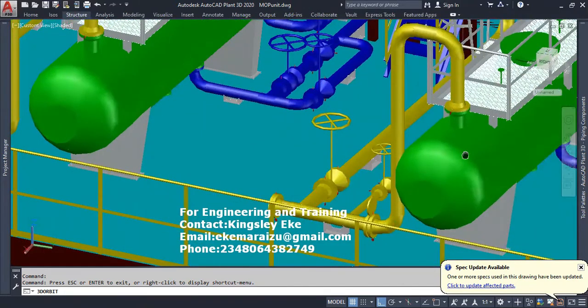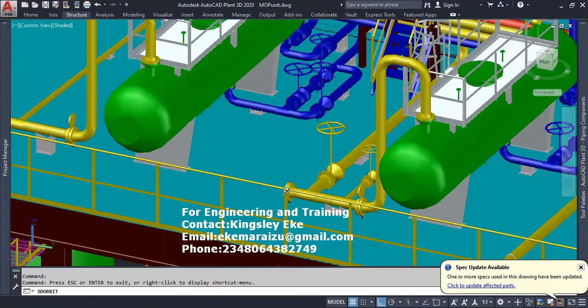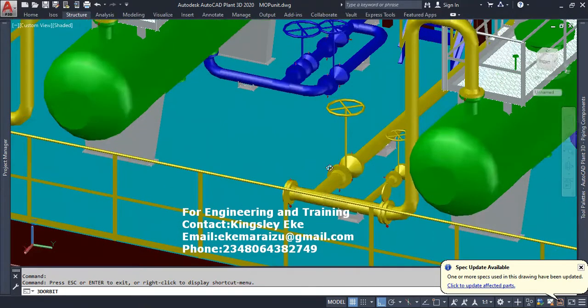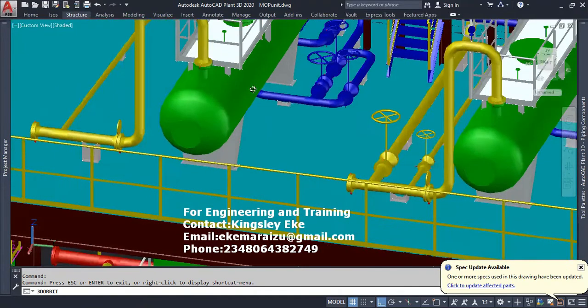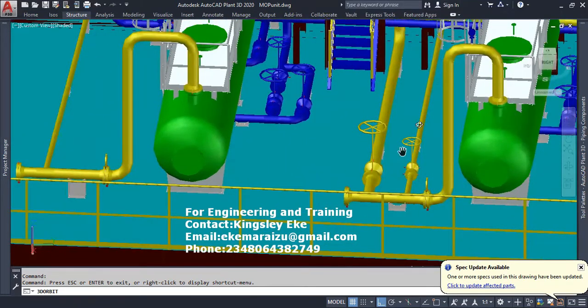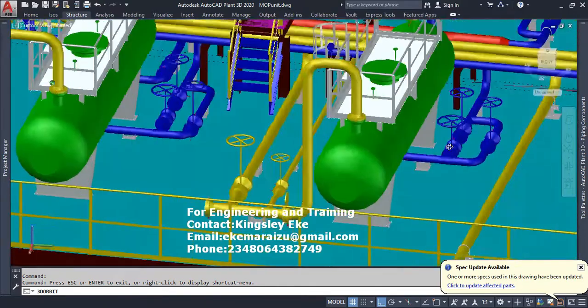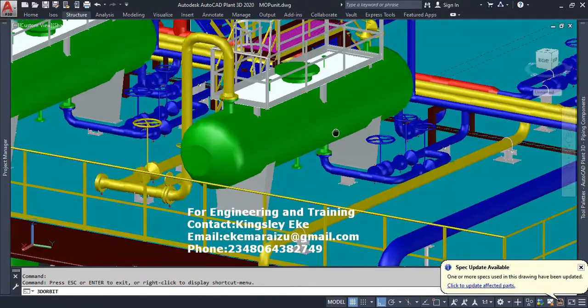separator. Now, crude also from a low pressure line through the LP header in the inlet manifold is tied into this flange together with crude from this high pressure line that comes in here, and crude from the test separator comes in here. They're all routed together to this LP separator that might be operating at probably 5 bar.